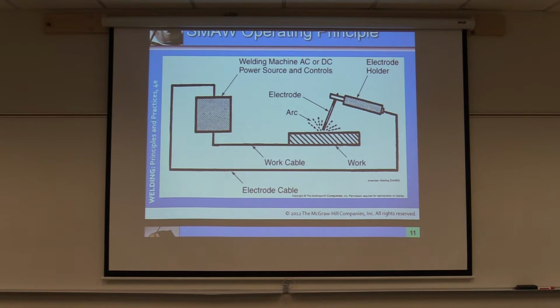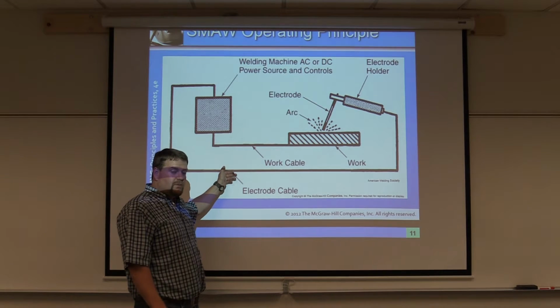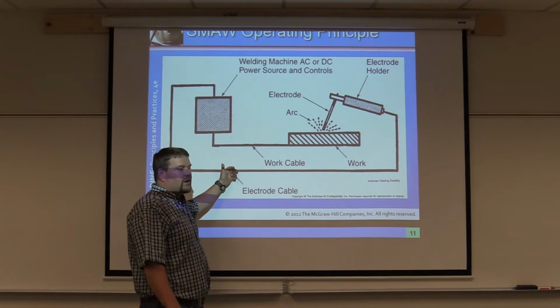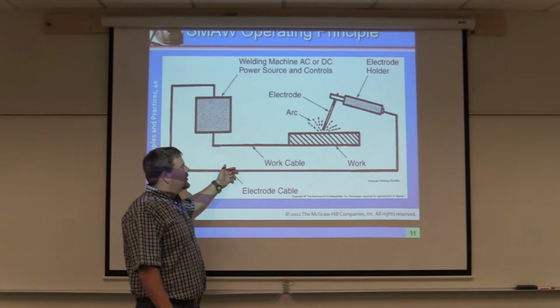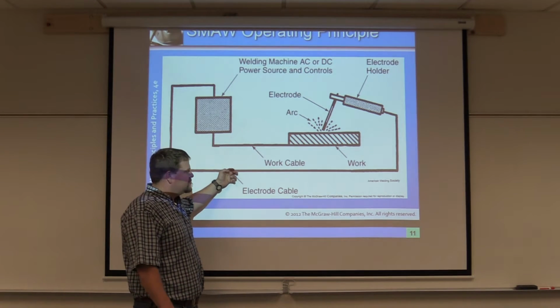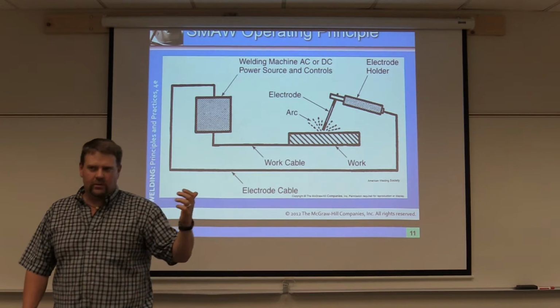Now your amp clamp, you use it to check your amperes. It has to be a DC type in most cases to clamp around here, because most of the ones that we use for electricity are an AC type amp clamp. That's how we check amperage. So you have to have a special amp clamp that's able to read direct current amperage as well.